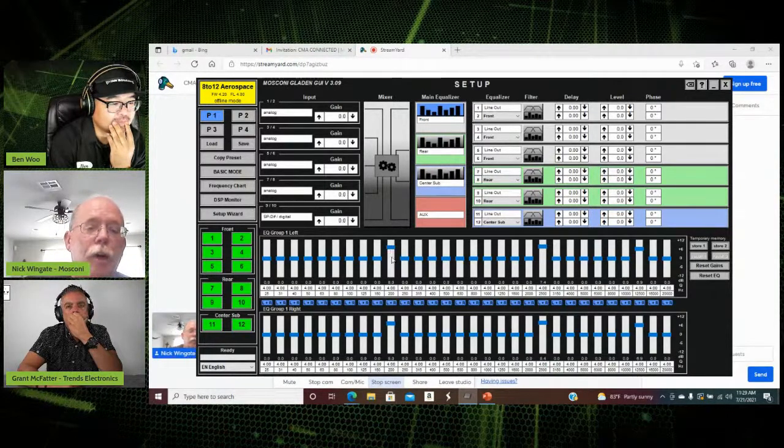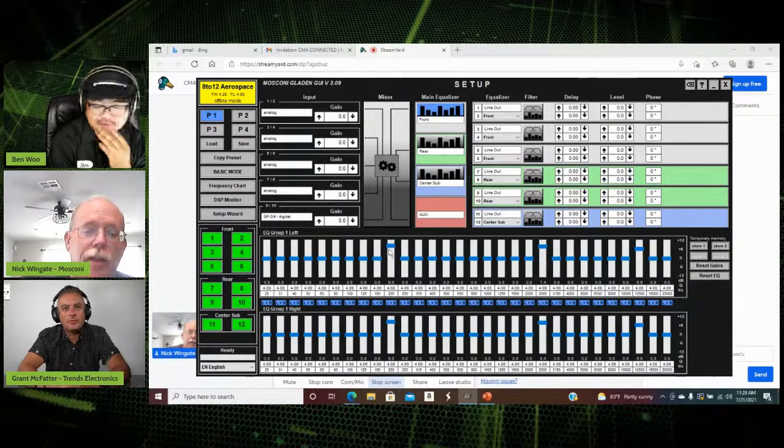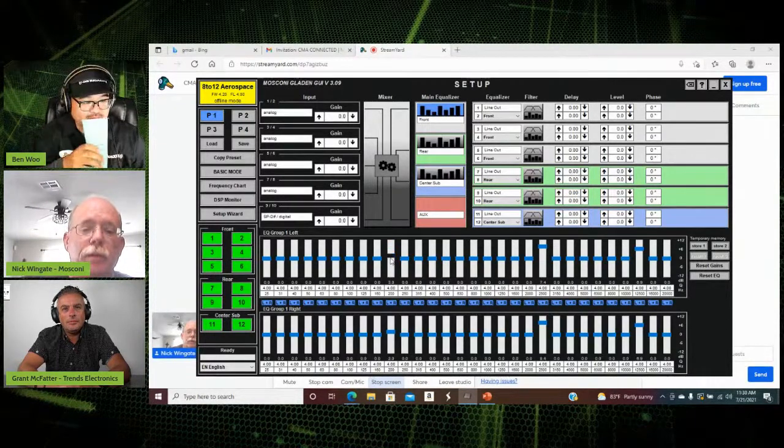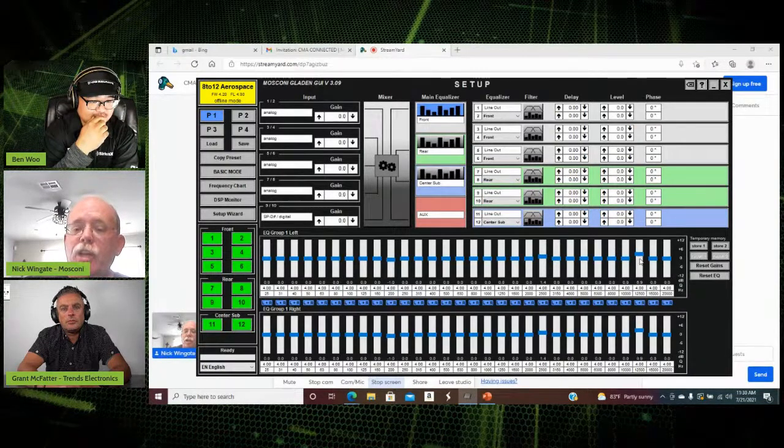So here we are at 8. So we're at 275% more power at 200 hertz. What's going to happen if you're playing EDM and it hits 200 hertz and it throws 275% more amplification power at that frequency? Bye-bye, driver. The speaker's going to do the bacon. Yeah, it's goodbye. Sizzling voice coils. That's right. This is the reason why you blow drivers, because people do this. And that's not what you want to do. So instead, when you have this issue, you do this. Okay.